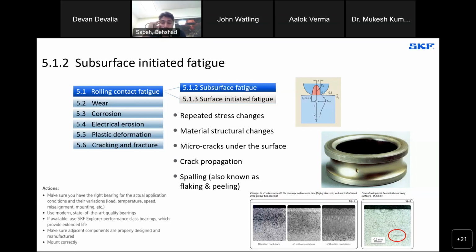Okay, so this was a deep groove ball bearing with a heavy, unnaturally heavy load, because the lab cannot wait years to get results, right? So this is a case of artificial conditions, and they are forcing the damage to occur in a time that they can pick it up.